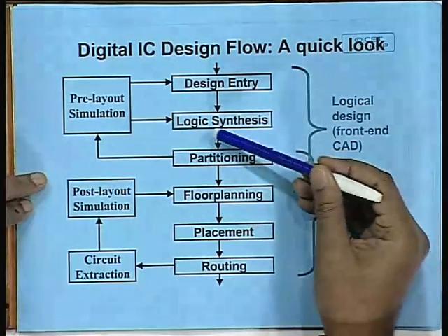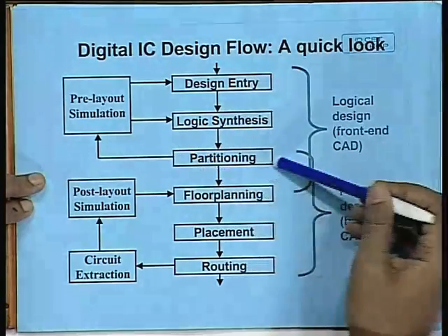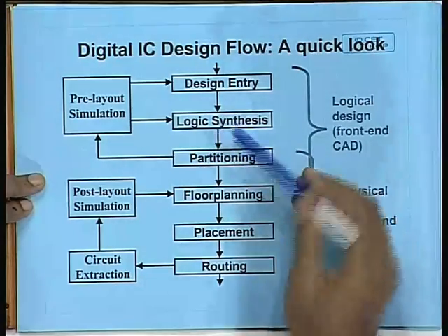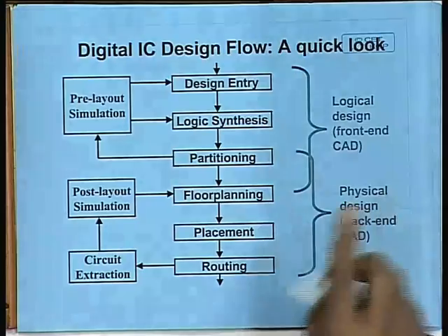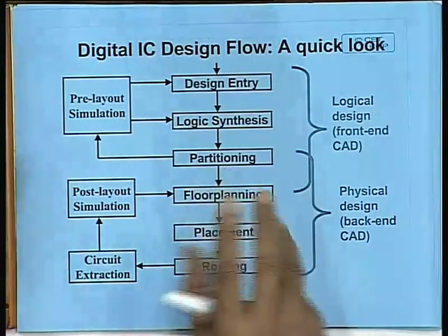Fine. So after you get it, you typically do some kind of a circuit partitioning because your overall netlist may be too big. Well, out here you do some kind of a graph partitioning to identify the tightly coupled modules, and the number of interconnections between two modules are less, so that it will be easier for you to place these modules on the floor of the chip.